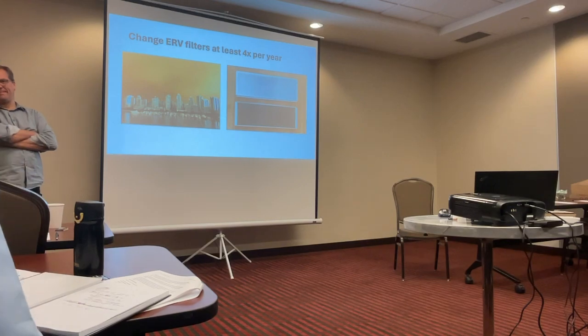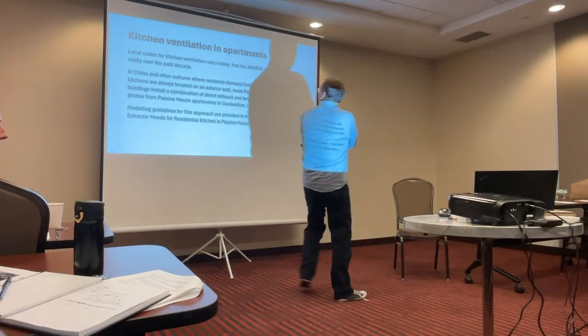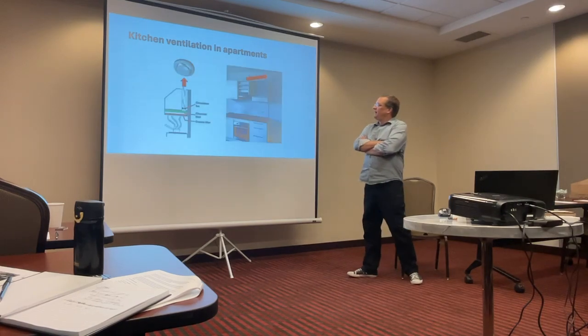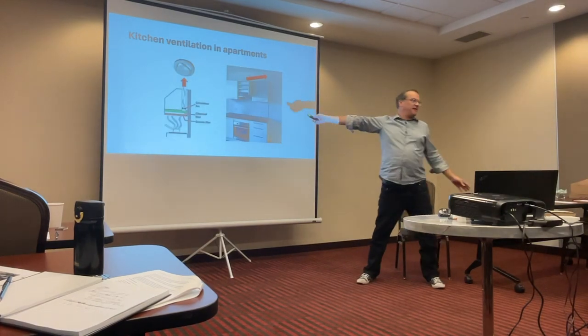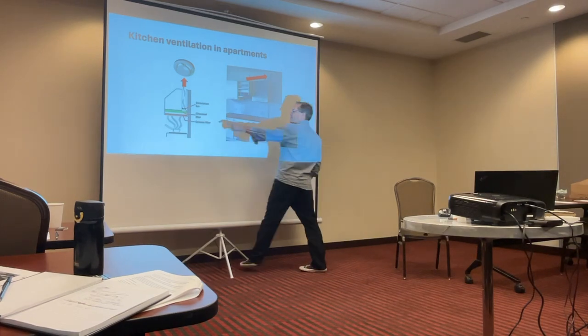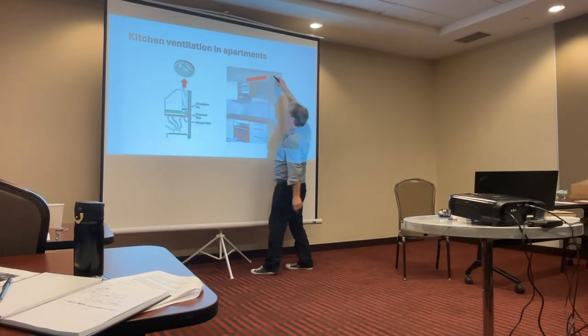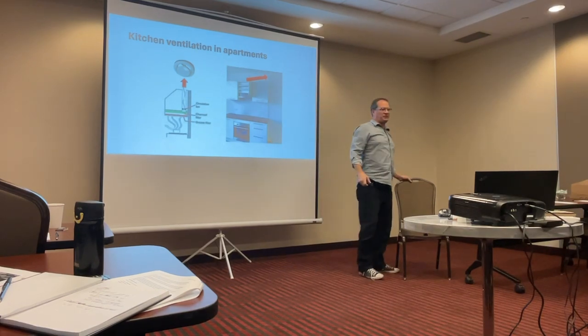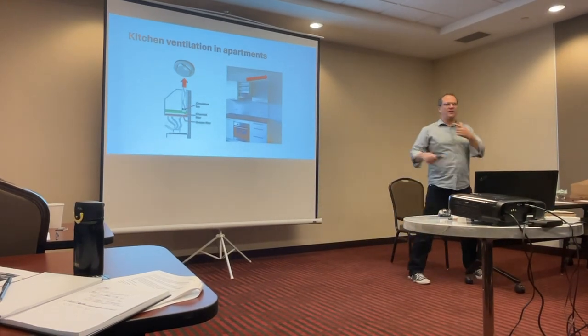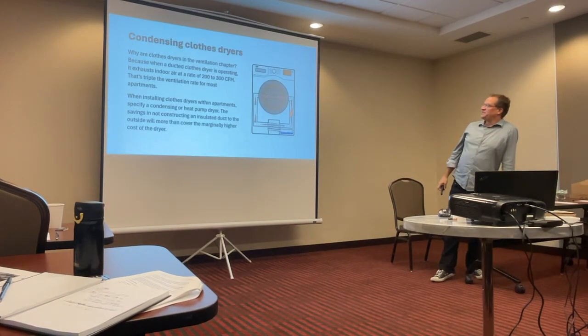Time check, 4:15. Because I know you're working on kitchen ventilation on the same. You know what? You can read the kitchen ventilation. Most of you know it. Our common go-to solution is a charcoal filter, a simple recirc fan if you can, intake to the ERV four to six feet away, whatever your code is. You have continuous circulation and you're beating down some of it at the stove. It's not the best, but it's what we're doing most in kitchens.